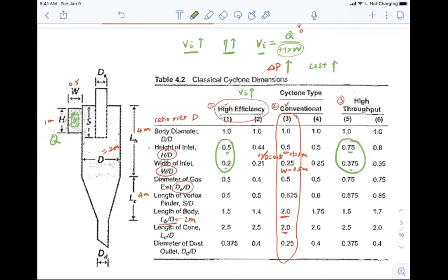high efficiency. And as a matter of fact, if we want to achieve high efficiency for removing particles, we could use other PM removal devices, for example, the electrostatic precipitator or the baghouse filters, okay? But the cyclones are the best device to remove larger particles, for example, above 10 micron particles, right? So this is why people can have these designs of the high efficiency.